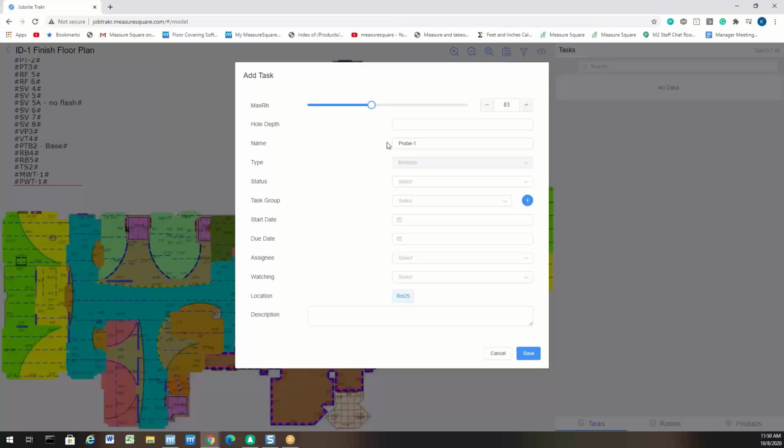After we're done with that, we will use the probe and place it into the drilled hole in the concrete at the predetermined depth to make sure we establish the initial value that we need. In this case, we will use half the slab depth. We will be putting 2 inches for the deep hole for the 4-inch slab, and you will see that there is a probe name. We can say the status of this task is open since we just started the job.